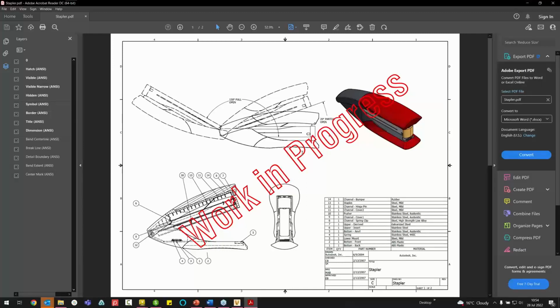And we can apply a plot stamp like the file state across the front and center of the file, to ensure that if someone like an engineer on the shop floor has printed a drawing, they are aware that this is in the work in progress stage. This is not necessarily an approved drawing. We can apply a plot stamp to the PDF or the DWF as well, my apologies. Ray, any questions in the chat you'd like me to go through?